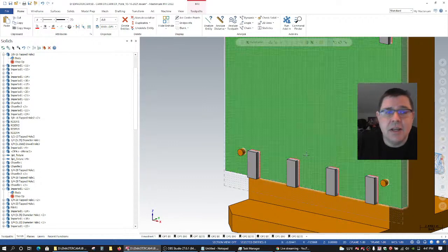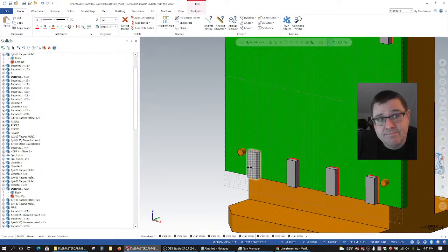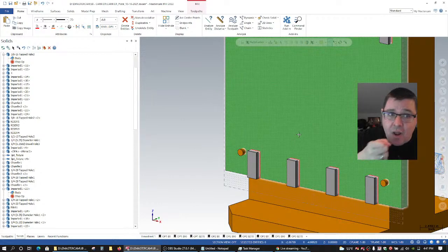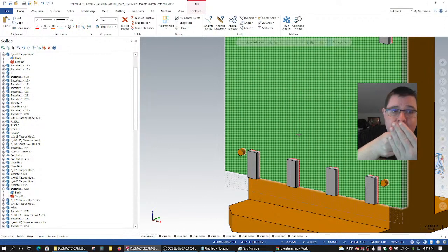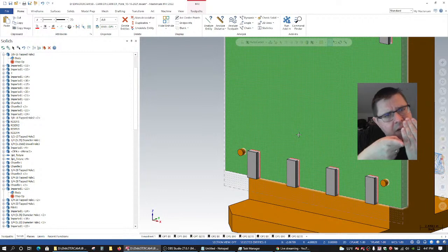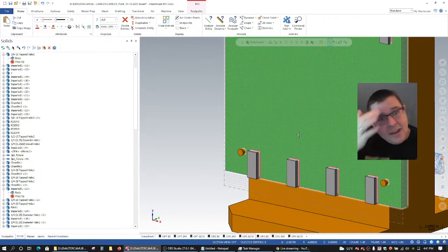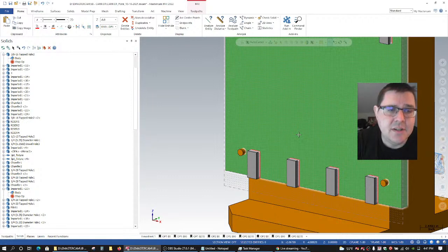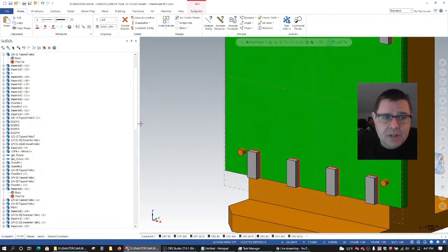I'm not even going to select the entire rectangle. I'm going to select the top face. Because if I'm coming in from the front, right, if my tool's coming in there, all I care about is a surface on top that I'm not going to violate. Because I don't care if there's a surface on the side, it's that top face that's going to prevent my tool from plunging down any further on that clamp.